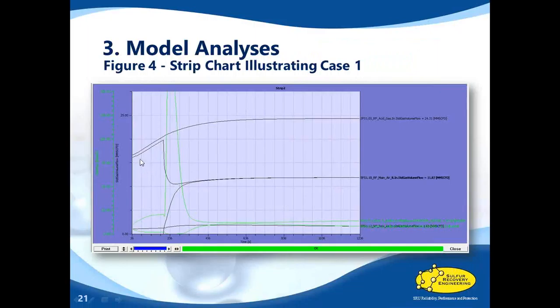We have our first blower ramping up. Oh, we need blower number 2 to ramp up at the same time. And in green here, we have H2S and SO2 at the condenser 4 outlet. We notice the spike that happens in less than approximately 12 minutes. There are some other factors that we had to look at, totaling the full 20 minutes to reach steady state.